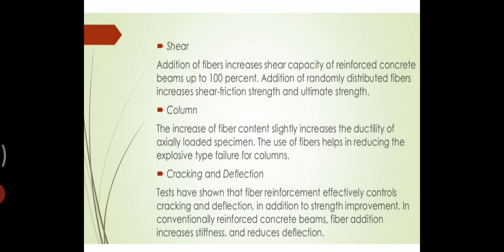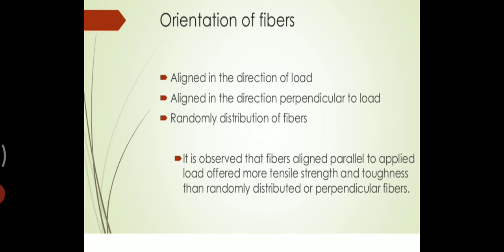Then cracking and deflection. Tests have shown that fiber reinforcement effectively controls cracking and deflection in addition to strength improvement. In conventionally reinforced concrete beams, fiber addition increases the stiffness and reduces deflection. Then let us see the orientation of fibers, how the fibers are placed into concrete.